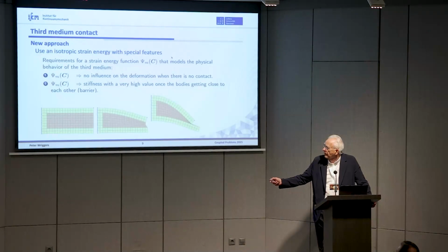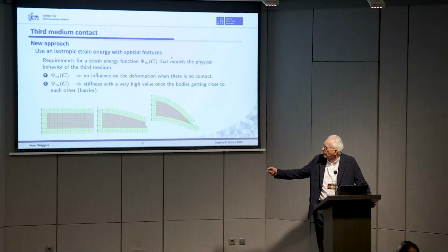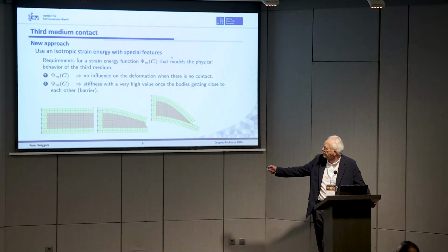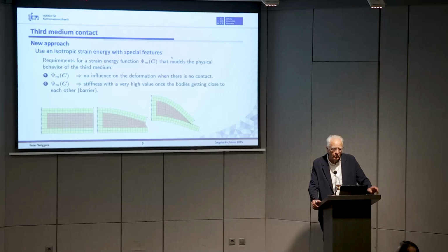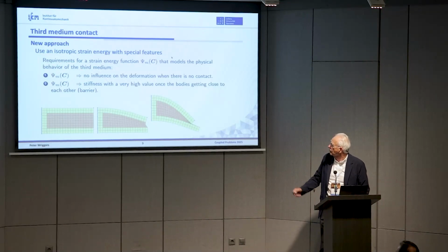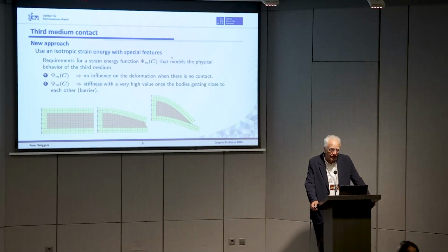This is sort of a problem which is loaded here and clamped there. So these are two beams. When you load it like this, the beam down here should not move. So there should be no influence of the third medium on the deformation of this beam. Only if it gets close, and you see here we can even model point contact with this kind of thing, it basically should deform and the stiffness should go very high.